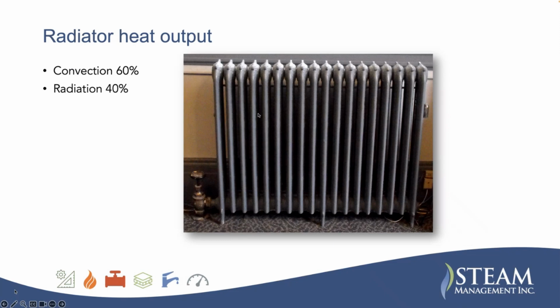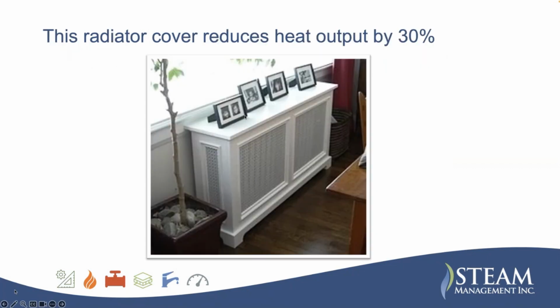Technically it's called that, but the heat output from this thing is 60% convection and only 40% radiation. So when you put that cover on here, we've lost the convection ability of the radiator. Now I'm only getting the 40% radiation. I'm losing 60% of the heat output.